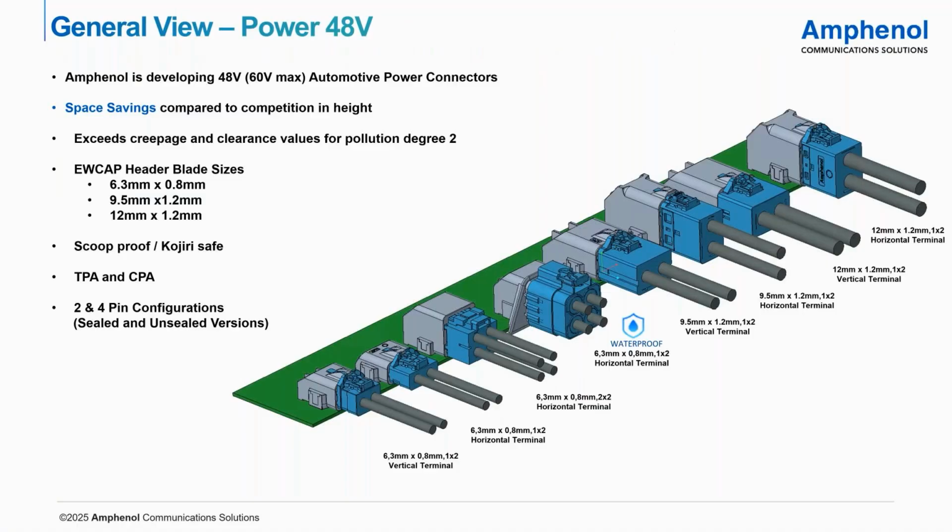Power. Amphenol did not have power connectors for automotive available, so we started to develop our power connectors for low voltage. We will have the range from 6.3, 9.5, and 12 millimeter versions with horizontal and vertical blades, waterproof and non-waterproof. But where we also want to differentiate from what we have currently on the market is on the 48 volts and on the size. So we try to reduce the size to have a mini version